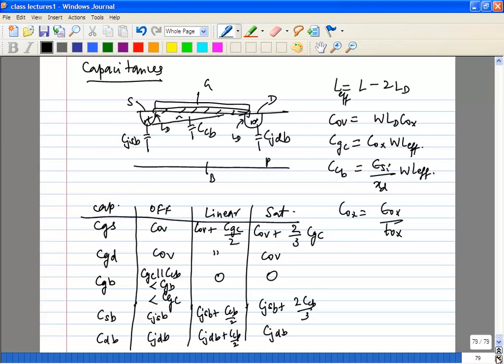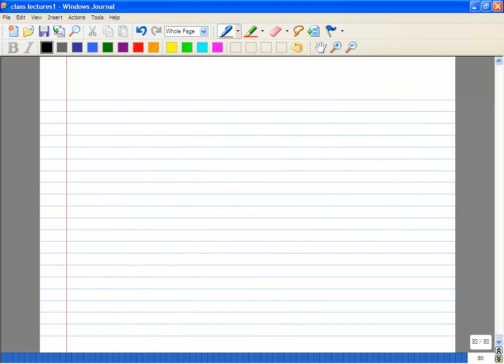So if you look at your MOSFET, you have the gate, drain, source, and the bulk. Remember, don't neglect the bulk. Anytime you have a transistor, make sure you bias the bulk properly, even in your simulations, otherwise it will cause all kinds of problems.